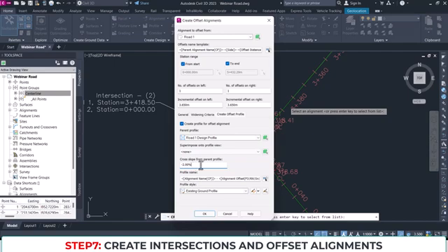So remember, our cross slope is 2.5%, if you remember the review that we did. If you are using 2%, you can leave it at that for your own road, but for this road it is 2.5%. And then the profile name, it will create an offset profile with this. Then it slopes it down by 2.5% at 3.65 meters, and then it will name it using this template. Let's leave it like that. So let's use the profile style as existing, design profile. All right, because it's a design profile, let's press OK.